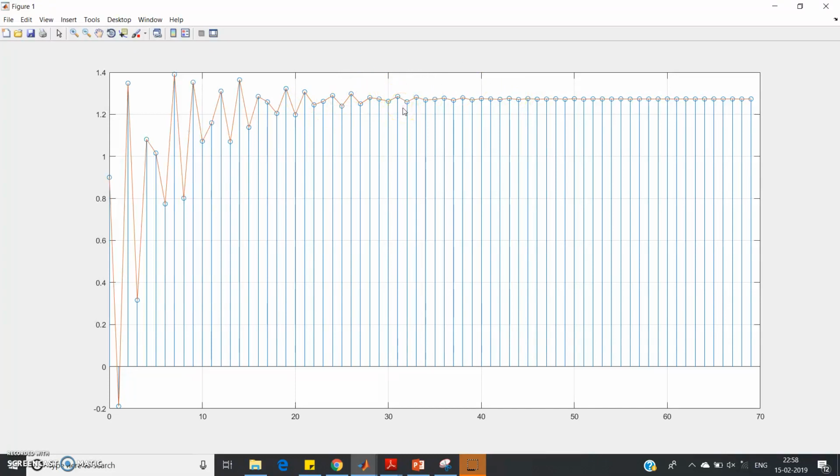So the definition is the time required for the unit step response to reach 2 to 5% of the steady state response. Okay, sometimes we take 2%, sometimes 5%, and according to that the formula will vary, which you will understand in detail from the control system point of view. But these terminologies I just wanted to show you to give a feeling about the transient response and the steady state response.